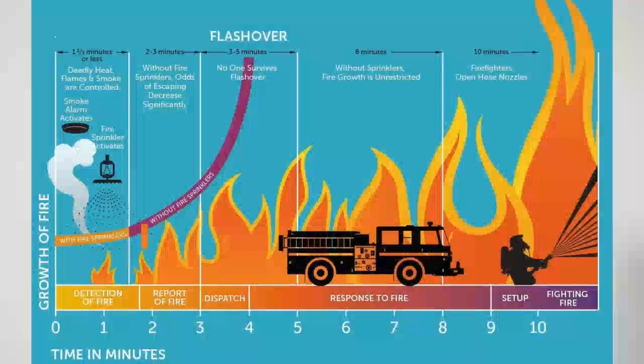And if you have fire brigades local to the premises, you possibly have water on the fire within 10 minutes. I'll give you an example of that. In the Highlands of Scotland, there's only one full-time fire station, and that's in Inverness. The rest are all temporary. So if you can imagine, they'll get the call out saying there's a fire. They've then got to get to the fire station, get changed, get on the truck and get away. Now that could be 20 minutes or half an hour before they actually get there. So this is the ideal situation. Oh yeah, that's the reason for installing sprinklers.